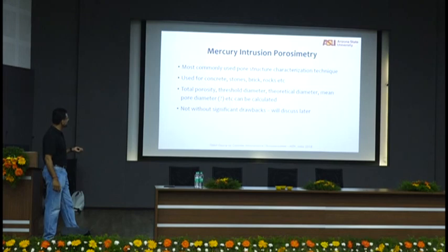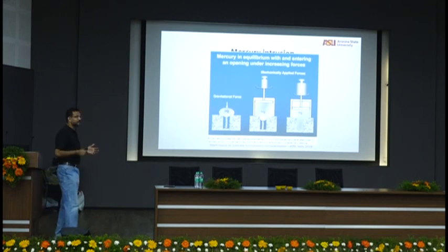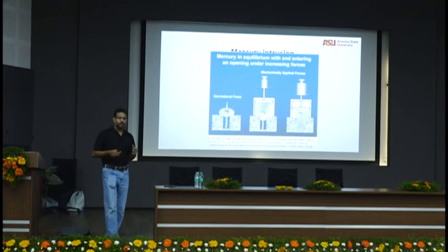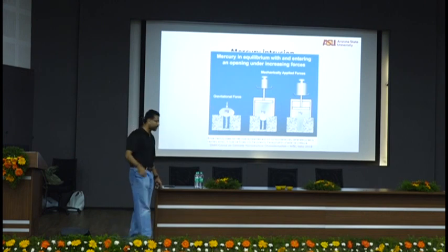Total porosity, threshold diameter, theoretical diameter, mean pore diameter, you can do a lot of things. A lot of drawbacks also there. So the idea is very simple. I take a liquid, I fill the concrete or cement paste with that liquid, and I figure out how much liquid I needed to fill the entire pore structure. That is my porosity, right? How much material I need to fill in all the pores is my porosity.